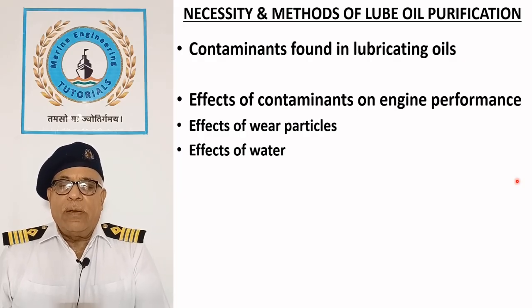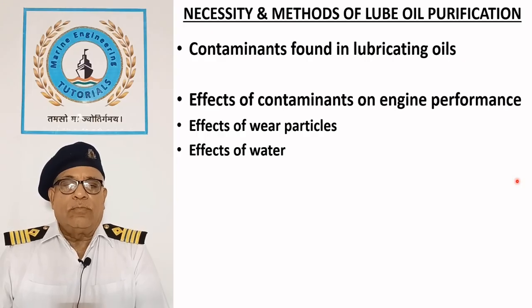It can combine with unburnt carbon to form acids and start corrosive wear. Water in large quantity emulsifies oil, which reduces lubricity and increases foaming and oxidation.